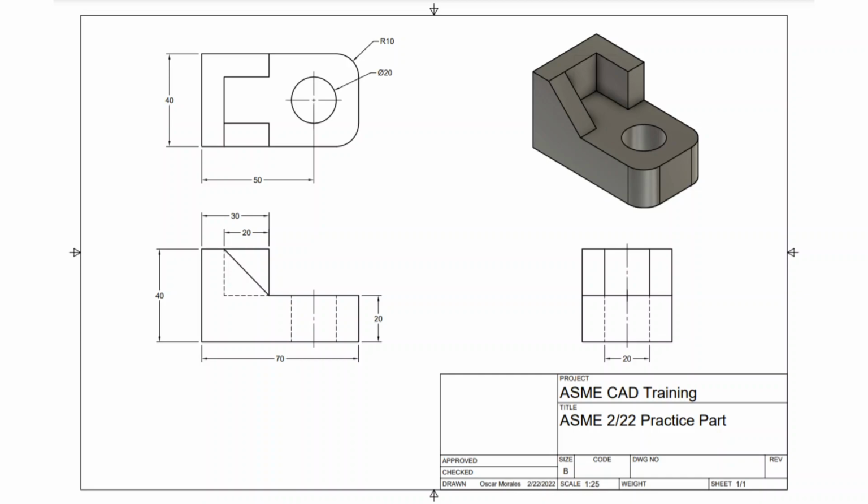Again, you should know everything, but here is something that we haven't covered. This shape right here is a center mark. So this plus marks the center of the circle. Right here, this little dashed line marks the center of a hole. If you notice, this circle and this are the same. This is the side view of that. So these walls are the diameter of this, and this dashed line is the center point of that.